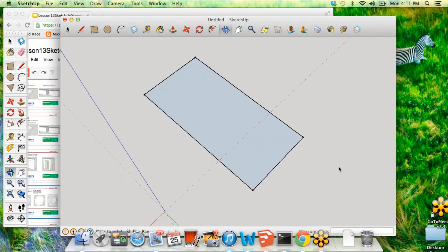Remember, the difference is that a square has equal sides. With this offset button right next to the rotate and the orbit, you start on an edge. You select a surface and an edge, and then you can move back and forth to see how much of an equal perimeter around the outside you want to create. And that way you get this even strip around the edge that's all the same size.